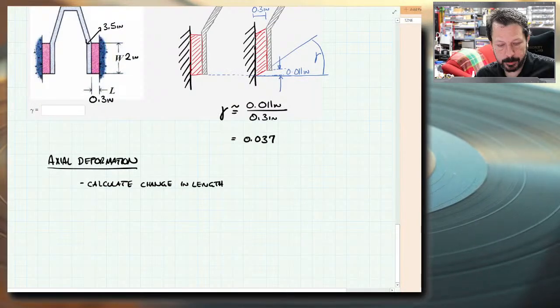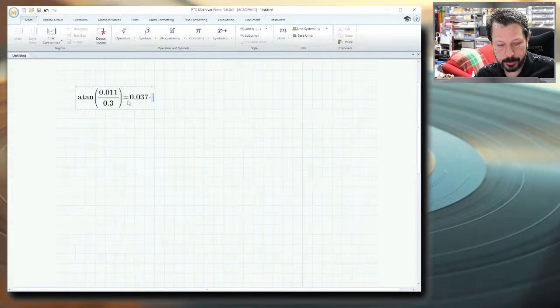So maybe you didn't get it converted over to radian mode or something. Maybe it's still mixing in some degree mode. MathCAD will do that if it's not set to automatically use radians, and the answer would be 0.037. If you got 2.1, then it's actually giving you degrees. So that could be what happened: if you got 2.1 for these two different things, then the 2.1 is probably degrees and you need to convert that to radians.